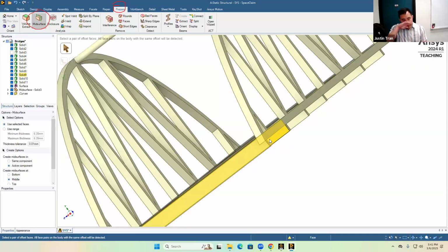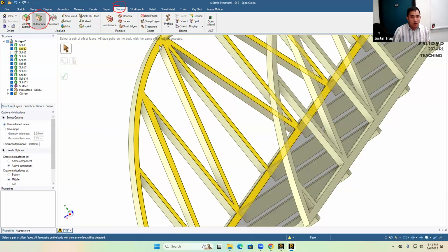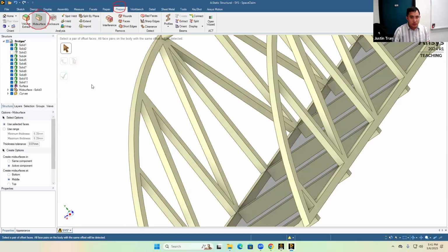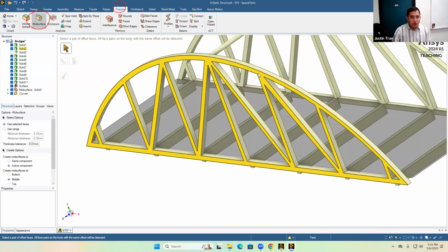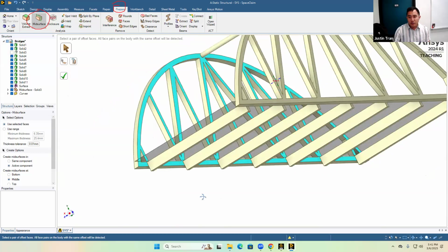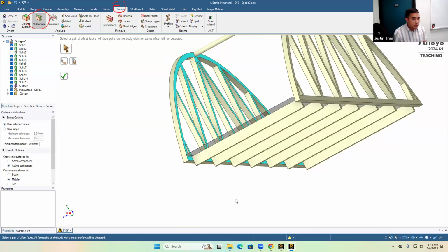Okay, all right, so let's go ahead and work on the sides of the bridge. The sides of the bridge we can also turn into shells, okay? So with the mid-surface operator still active, go ahead and click on maybe the inside surface of the bridge, okay? And then scroll around and click on the outside surface of the bridge, the one that's perfectly parallel to it. Once again, you're going to see that both surfaces highlight. One's going to be blue, one green. This tells you that ANSYS was able to find that these two surfaces were indeed parallel to each other and separated by a constant distance.